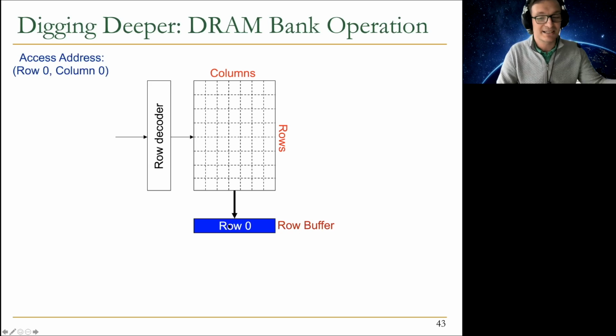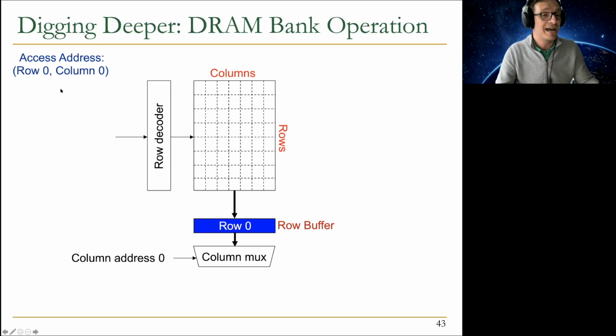Now interesting things start happening. You can send the column address and get the column that you want, column 0. Basically, you send this command, give me the column that I want, and column 0 gets multiplexed out from the data part. We're going to see this multiplexer also soon in the combinational logic lecture, in fact tomorrow and next week. So you're going to know exactly how the decoder gets built and how the multiplexer gets built.